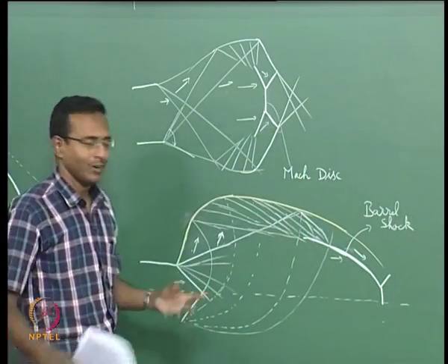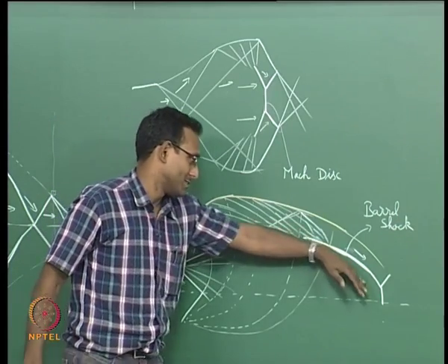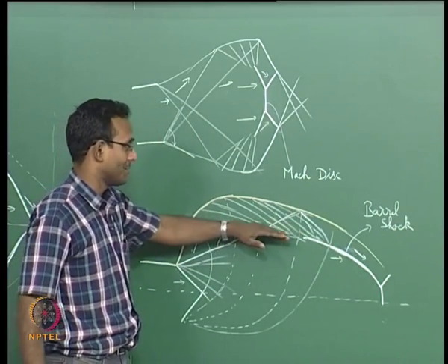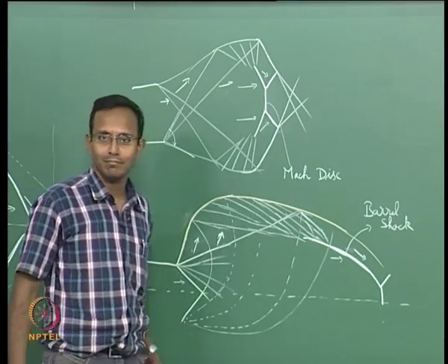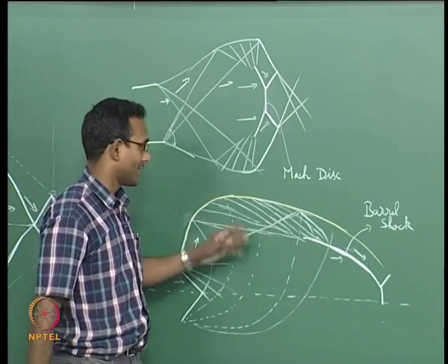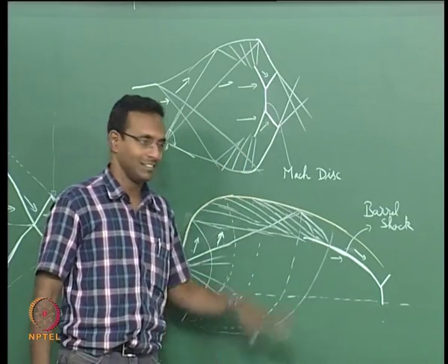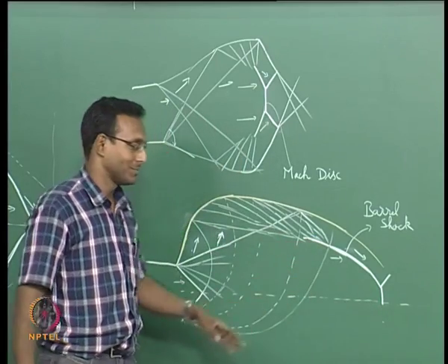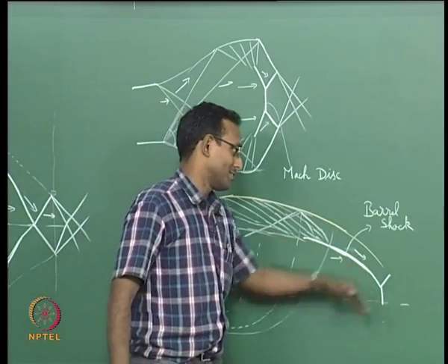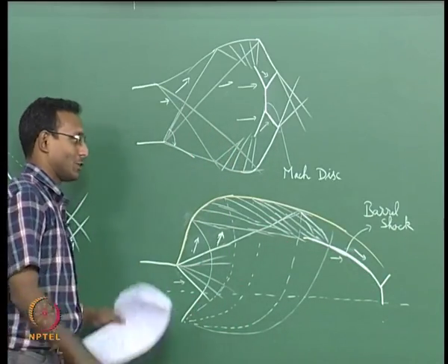Barrel shock. Why? It looks roughly like a barrel. It is not a complete barrel, but it starts somewhere here and it just goes like a barrel for storing liquids. That kind of barrel just looks like that. And at the end it has a Mach disk like the top lid of your barrel or something. Going to look something like that. So, that is a barrel shock.